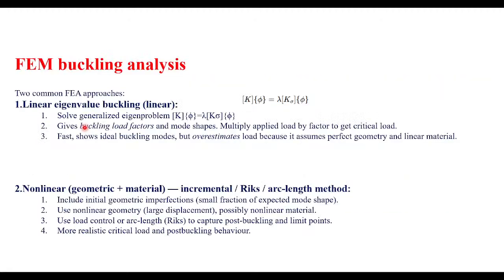Okay, so just to get deeper into linear and non-linear buckling, you could see we have two scenarios. If you want to do the buckling analysis, you can simply carry out the linear buckling analysis, that is a linear eigenvalue buckling. In short, this is the formula we use. What it does is it gives us the buckling load factor, and also the mode shapes.